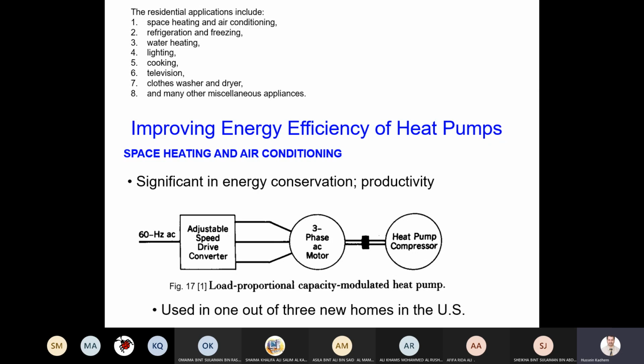Okay. Now, what is the problem here? The problem is this motor compressor absorbs a huge amount of current, a large current, and a huge amount of energy and power. I mean, talking about between 10 to 20 ampere when we talk about 220 or 230 volt, we are talking about around 2,000 to 3,000 watt, which is huge.